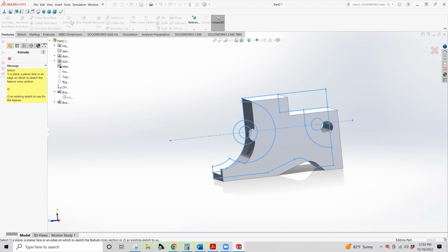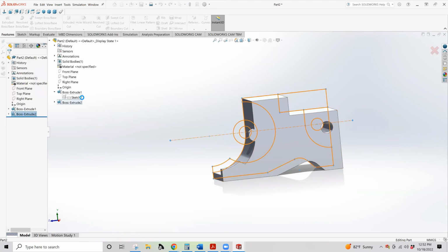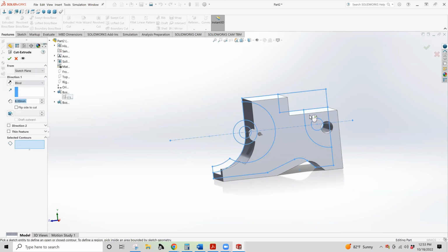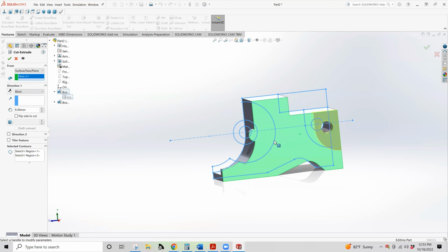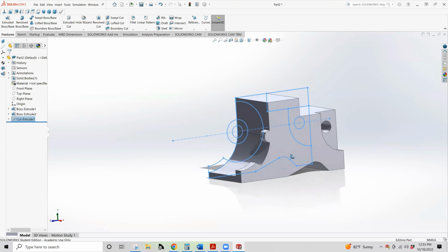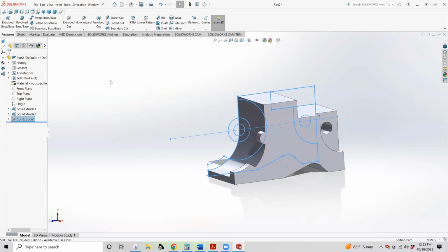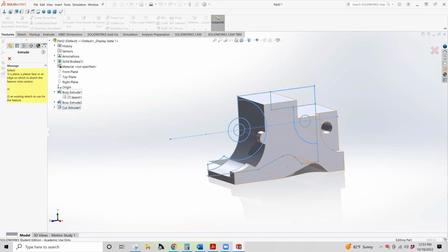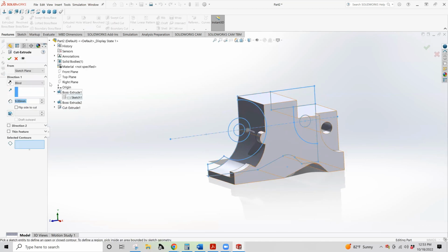No, it's not. Okay, so we're going to do a couple stages. So extrude cut, we're going to do this region. And this is going to be 9 millimeters worth from surface, which will be this face. So 9 millimeters worth on that first cut. It's possible to do multiple depths of other things, but it gets to be harder than what it needs to be. So don't try and do 18 different depth cuts with the same operation. Just do multiple as a general rule.